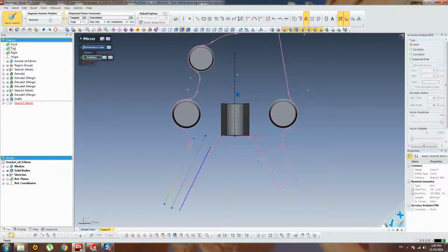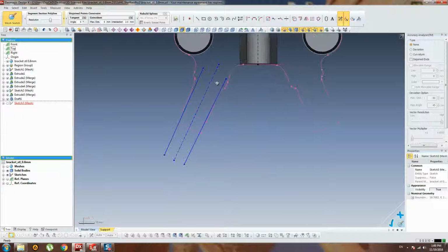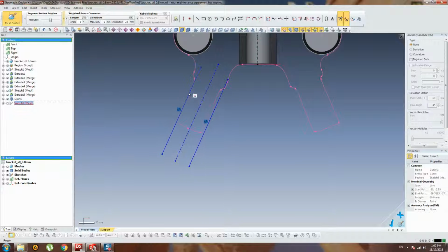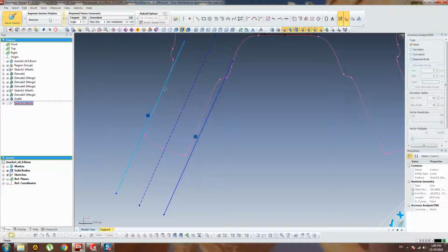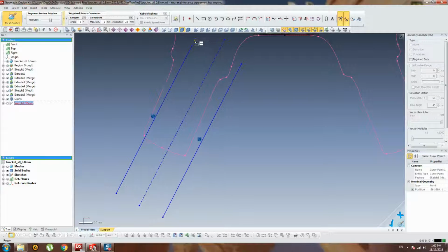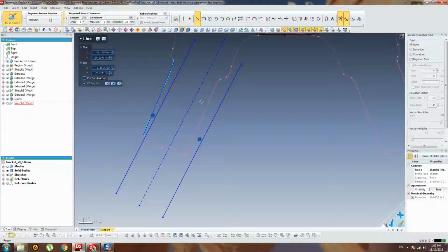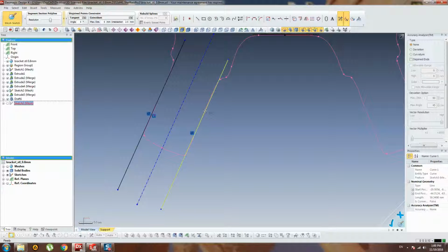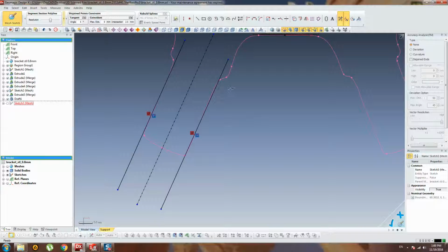And make another direction symmetry line for cylinder. This line should be parallel here, and try to find dimension of the cylinder. You can move, something like this. You can approximate it by line, but not correct. Need to make it manually. Something like this. Yes, move there, fix, and move this one here, and fix. Connect these ones together.